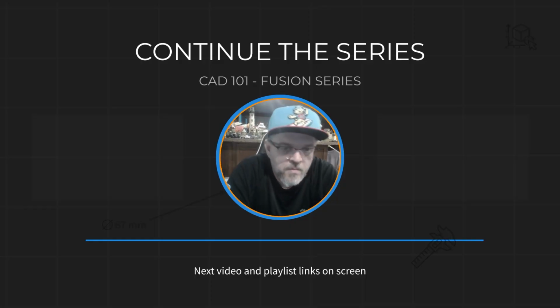And there we go. Our model rocket is now fully assembled. We started with individual parts earlier in the series, and in this episode we brought everything together using the assembly workspace. You saw today how joints allow us to connect components, how rigid groups lock parts together so everything behaves as one, and how the circular pattern allowed us to easily duplicate features like our tail fins evenly around that rocket body tube.